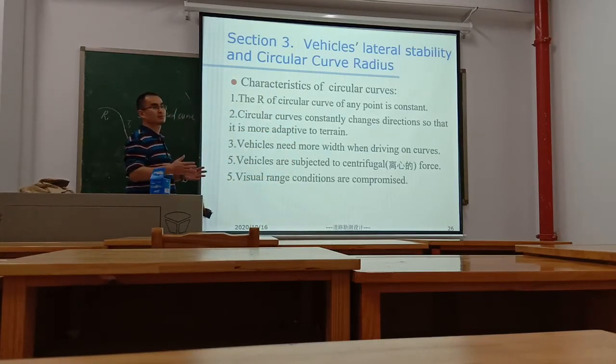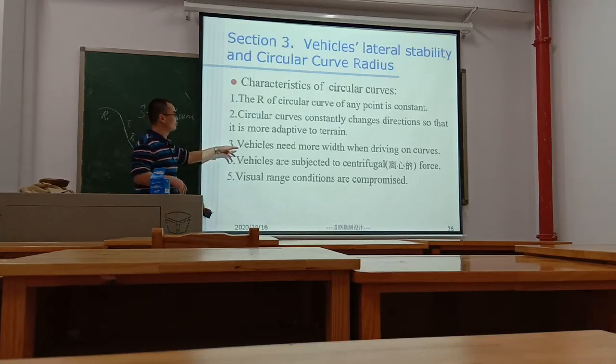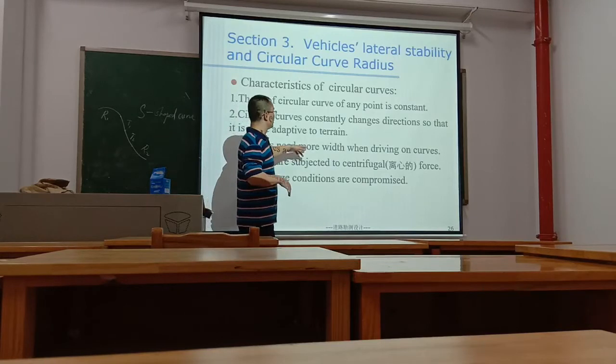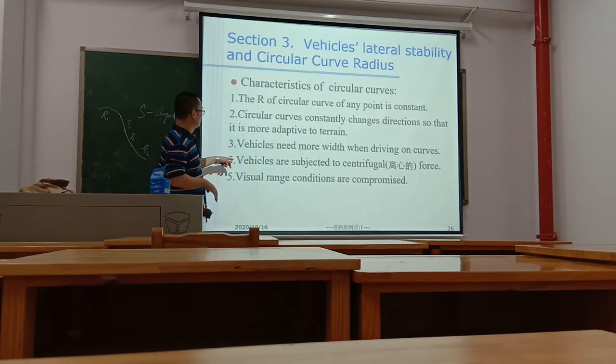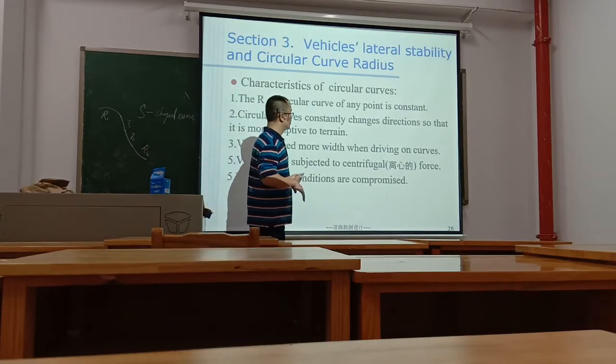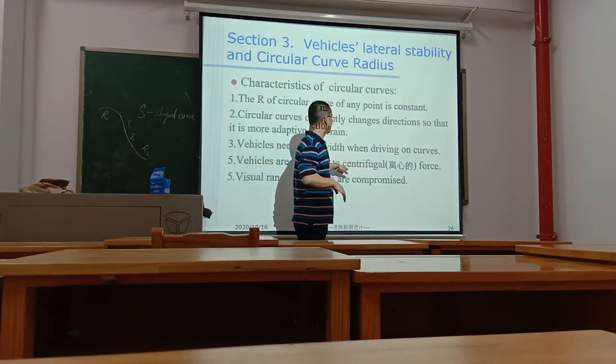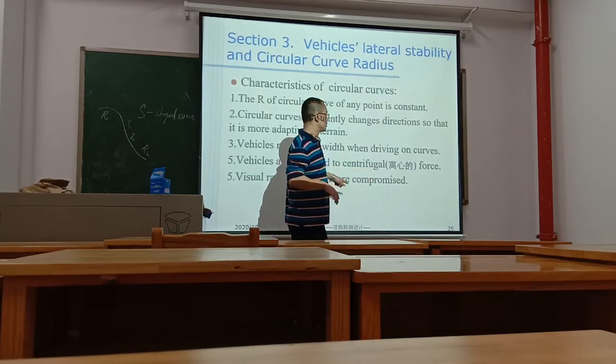Because vehicles have a length. Some trucks have a very long length, so vehicles need more width when driving on curves. 4. Vehicles are subjected to centrifugal force.